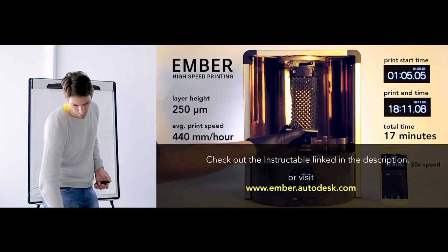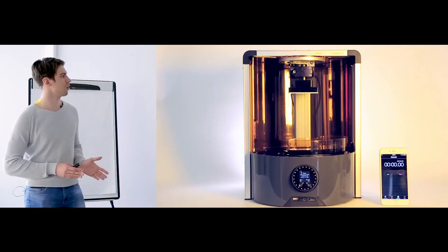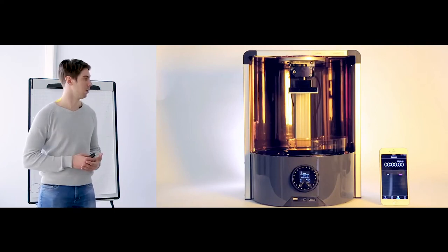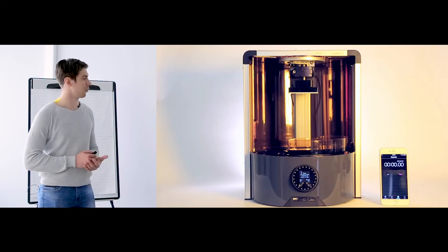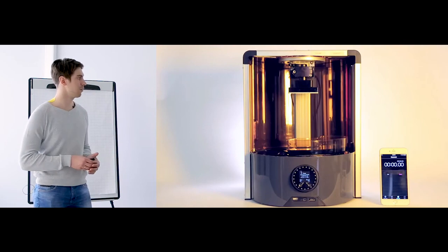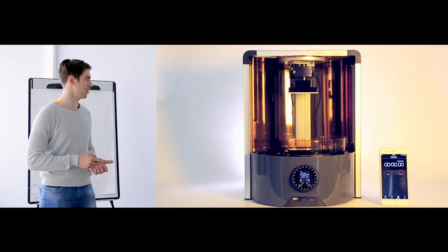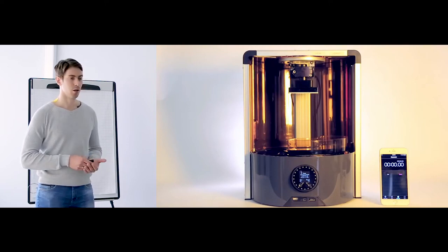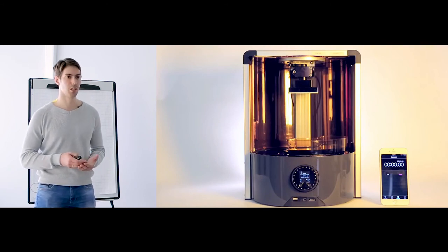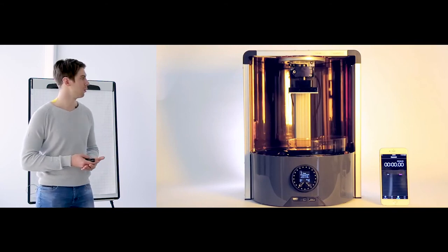What's interesting about this video is that this video combines two very important things about stereolithography bottom-up printing. So the one, as the video said, the first 11 layers were printed by pushing the platform to the side, which is necessary due to the big suction forces which take place when your building platform is close to the transparent window.